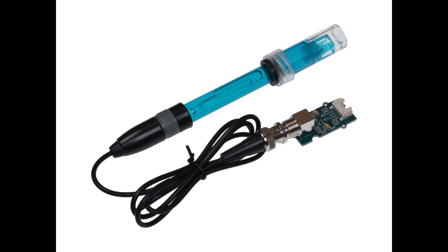A pH meter is a scientific instrument that measures the hydrogen ion activity in water-based solutions, indicating its acidity or alkalinity expressed as pH. The pH meter measures the difference in electrical potential between a pH electrode and a reference electrode, and so the pH sensor is sometimes referred to as a potentiometric pH sensor. The difference in electrical potential relates to the acidity or pH of the solution. The pH sensor is used in many applications ranging from laboratory experimentation to quality control.